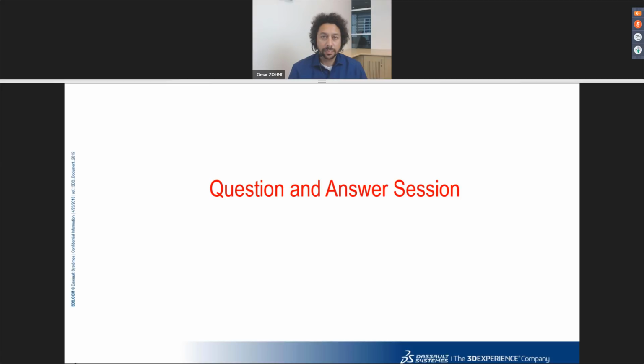So typically, if that were a cylindrical cover or a rectangular cover, you would gate where Jesse was showing. But if that were a connector, or if that part had a lot of core outs, you probably want to consider gating more on an end. The beauty of the simulation software is you can move that gate around. You can see exactly what's going to happen. But just so you know, by default, the simulation software is going to look for the shortest flow length. That's what it tends to look for.